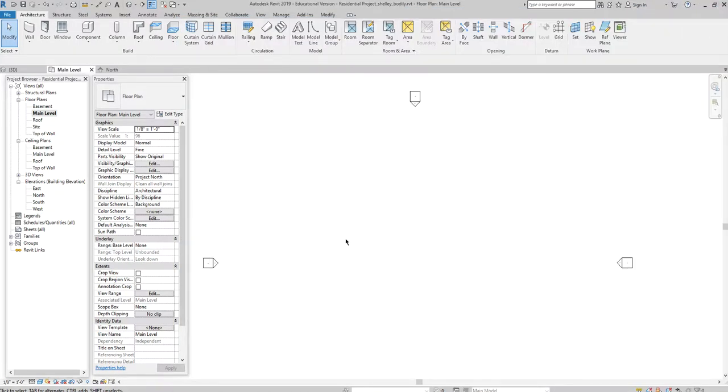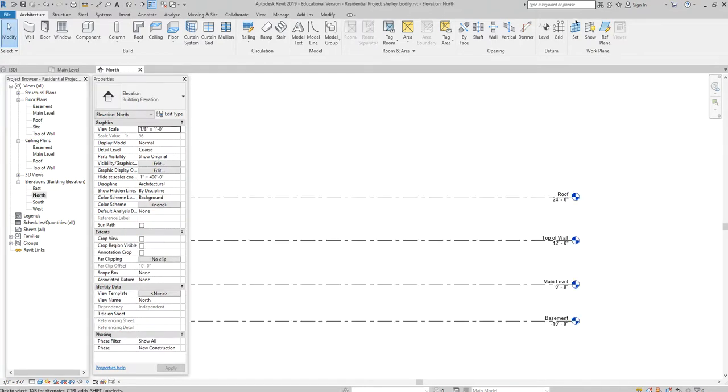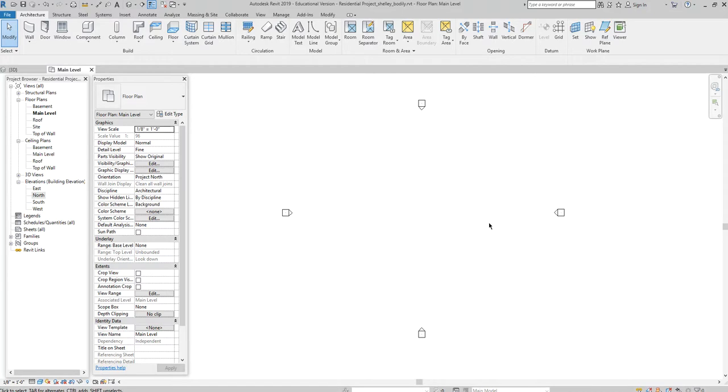Grids are really easy to use, all right? And we can create a grid in a floor plan view. I was just thinking, oh yeah, you can, I guess, or an elevation view. I've just never done that before. I think probably I've never done that before because it makes sense to draw a structural grid in floor plan view. But a structural grid, or whatever type of grid that helps you organize your architecture, whatever you're drawing, is always very helpful, right? So I want to show you how to add grids, okay?